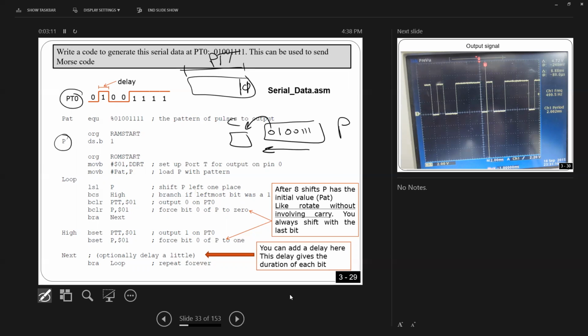Okay. So this is how it is. I'm going to do a loop. In this loop, in every iteration, I'm going to shift to take one bit, and then I'm going to check this bit, and then I'm going to output 1 or 0. Is that okay? One more thing I'm going to do is, every time I shift, as I explained before, when you shift in a 0, I'm going to copy this bit back here. Why do I do that? So that after 8 shifts, I'm going to get the number again and repeat. You got what I'm saying?